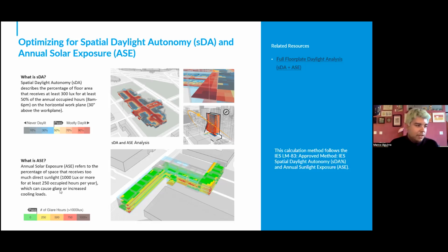That's usually from around 3 to 5 p.m. on southern and western facades, where people get really uncomfortable. It's hot. Again, these are just uncomfortable conditions for your occupants. It's something that you want to think about, and it can also increase your cooling loads as you need additional air conditioning in order to make that space more comfortable.